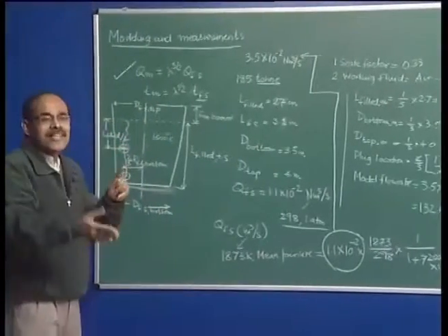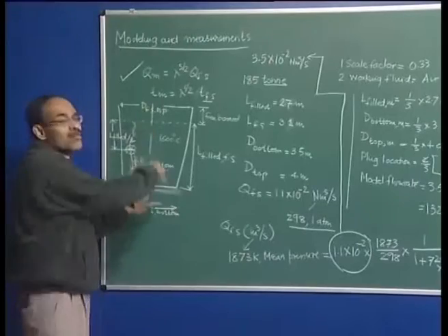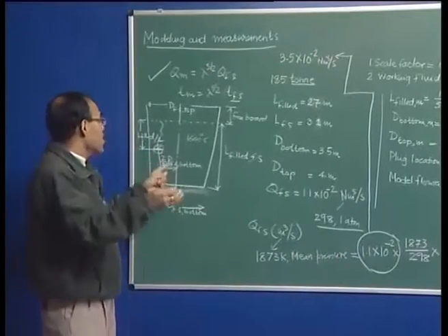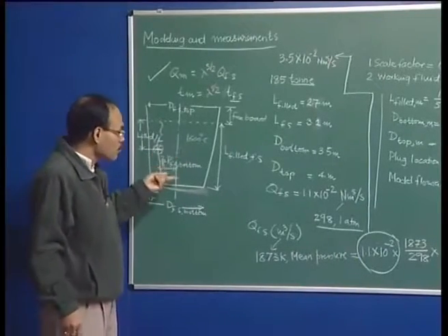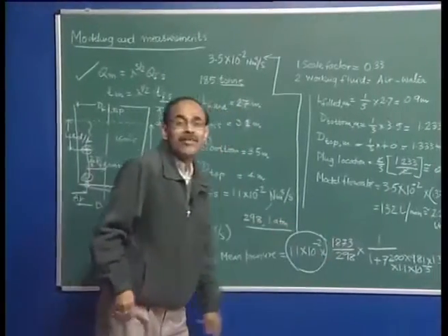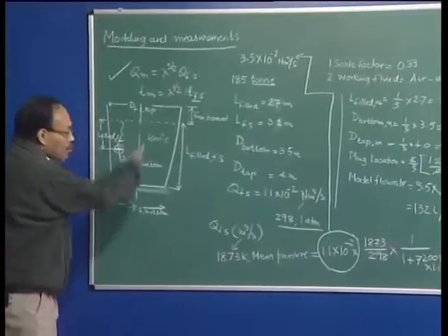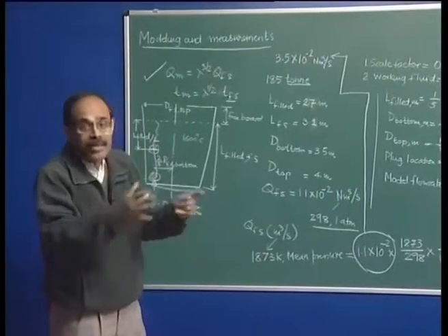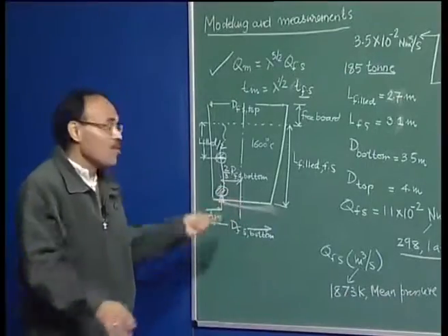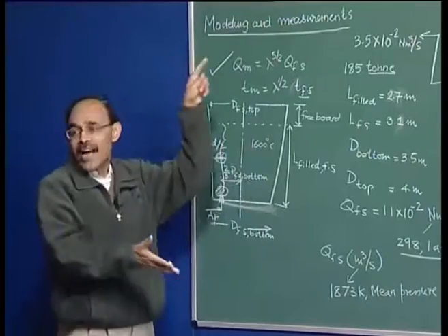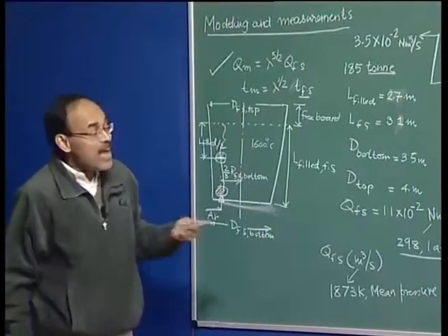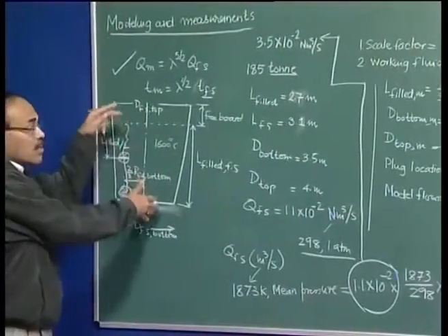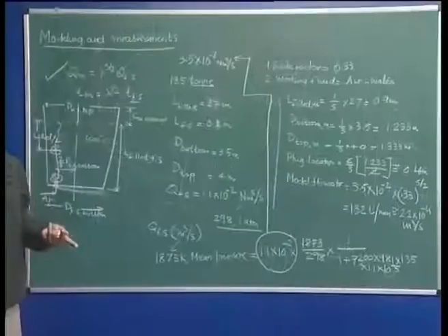So, because of pressure temperature difference, the water temperature mostly is going to be room temperature. If it is a hot weather, maybe water temperature is going to be 26. If it is a cold day, the water temperature may be 10 degrees or 12 degrees, but it is not going to be significantly different. So, even if we are injecting the normal meter cube gas flow rate, the normal meter cube and meter cube per second will have no consequences when water models are concerned, because of two facts: that the temperature is not very high and that the density of water is not as high as that of steel, which is 7-fold larger. So, therefore, pressure temperature correction of the flow rate in water model systems is going to be insignificant.